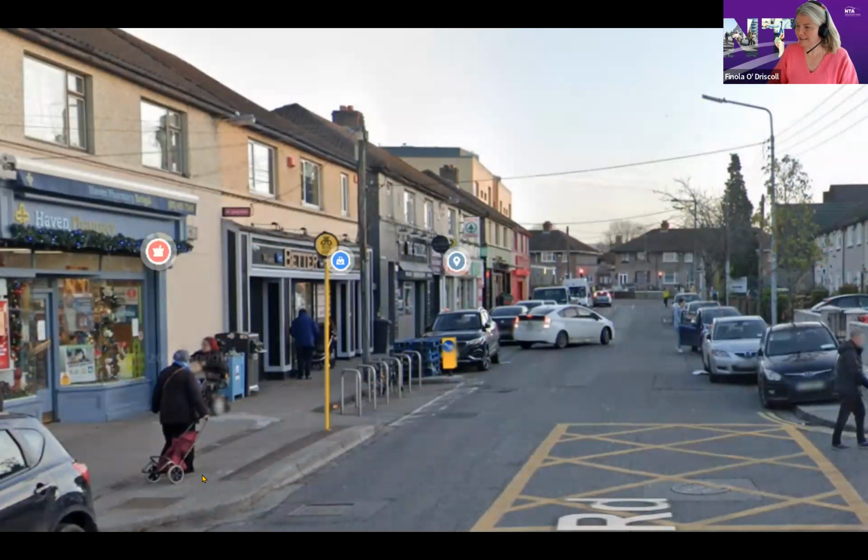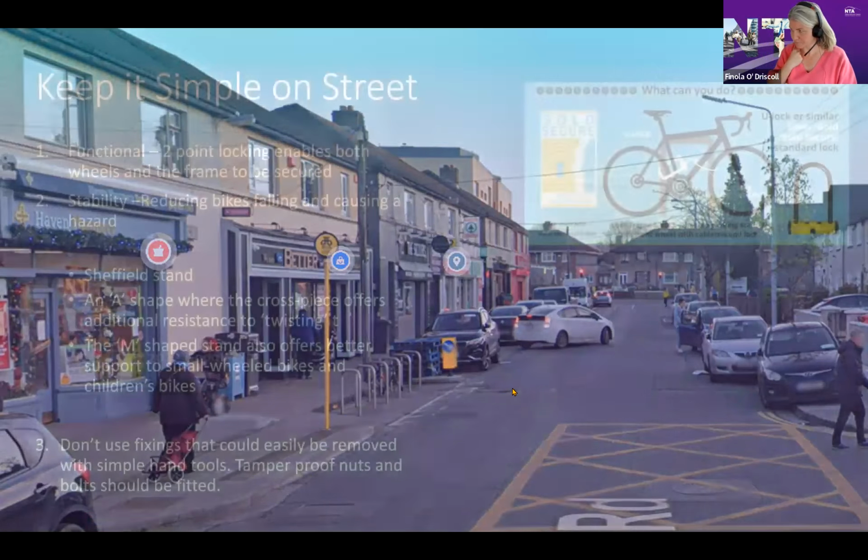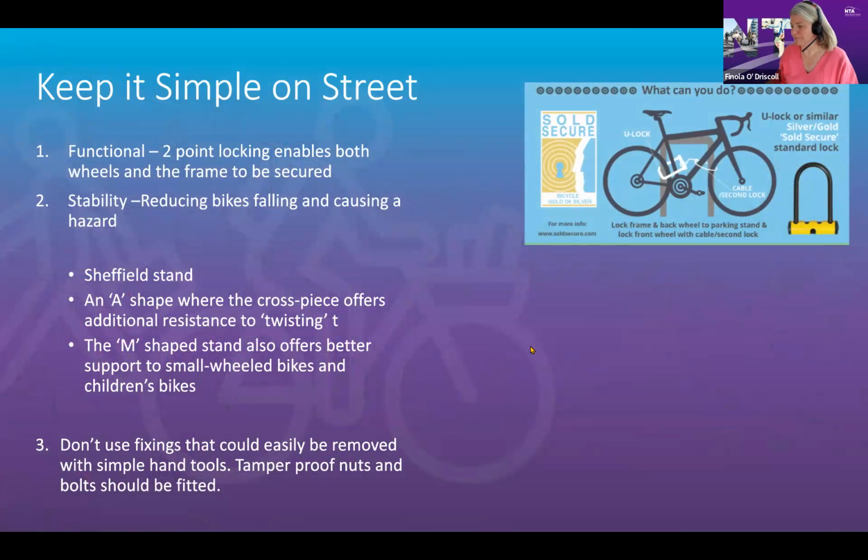But you can see we are more and more building bus stop borders. Guidance on bus stops, as you know, in urban areas we're not looking for laybys. They're problematic for bus operations. It's really hard to both get in and out of them. There's nothing wrong with a bus stopping in an urban area in a street to load and unload passengers. So where we've more of these bus borders, there's a good opportunity to co-locate cycle parking beside them, and it stops people parking where that might impede bus access.